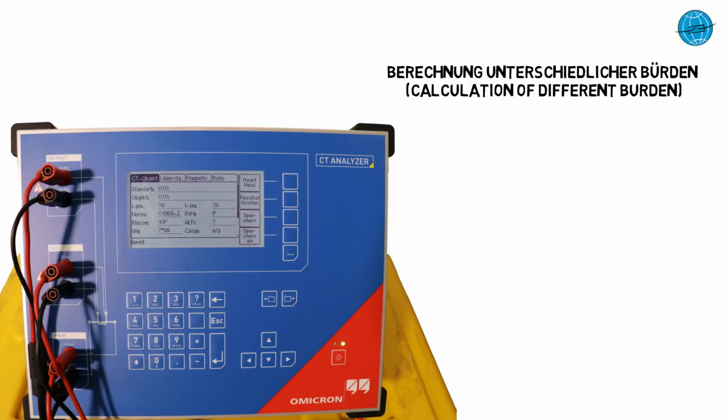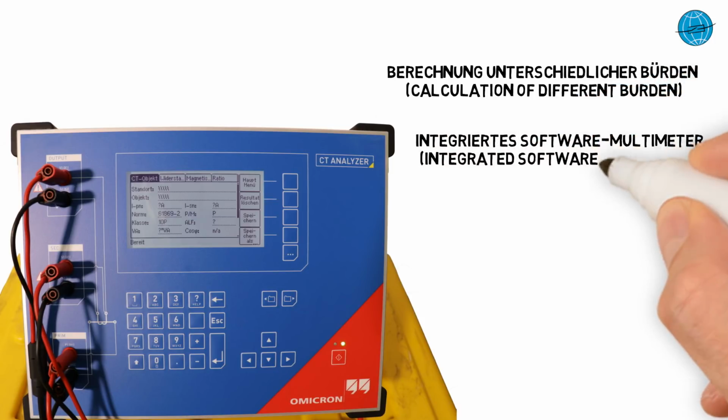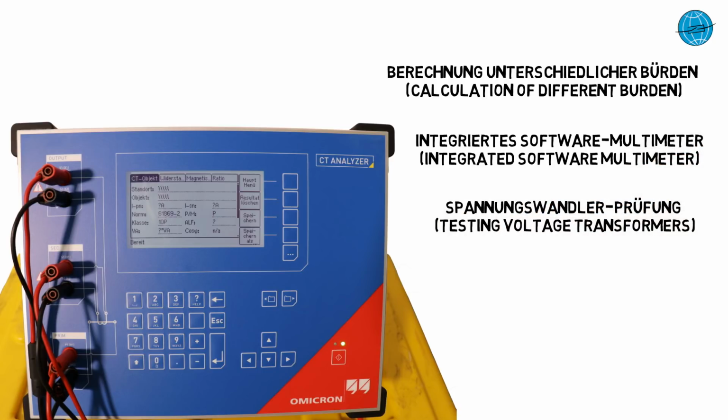Furthermore, the CTA has an integrated software multimeter with which manual tests can be carried out. Here, ohmic and inductive resistances or impedances, as well as polarity and burden, can be measured. In addition, Omicron does not do much advertising with it, but the CTA is easily able to determine the ratio of inductive voltage transformers.